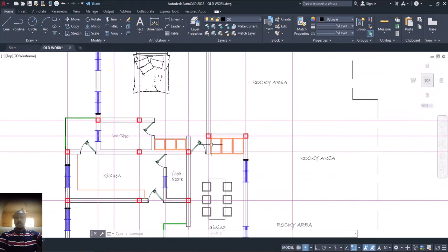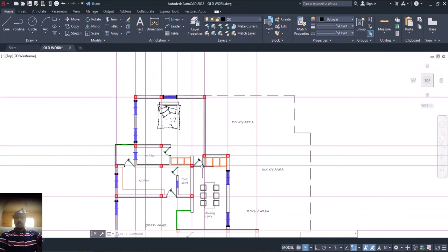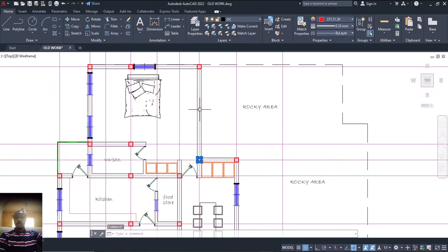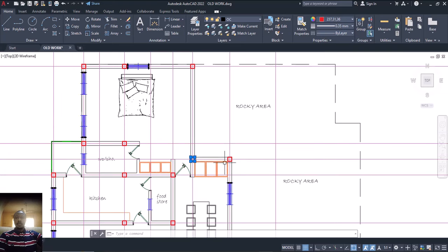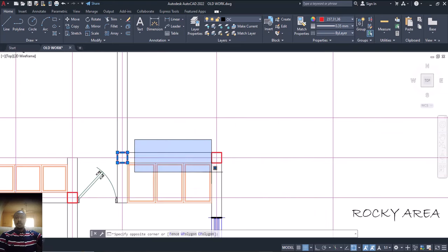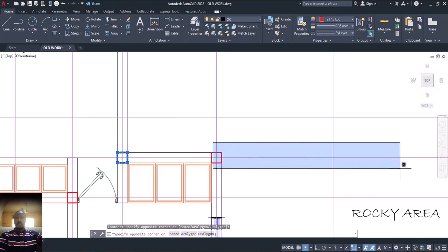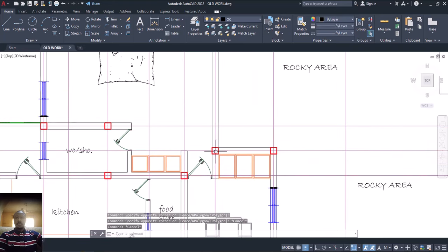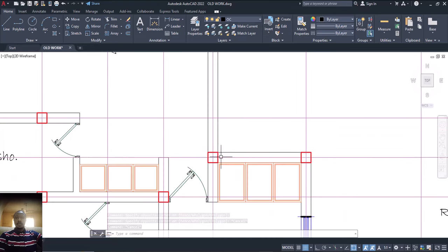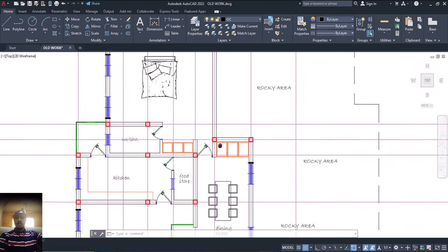Now looking at this place, they seem to be very close. But the way the architect does the drawing at times also matters a lot, because if I remove this particular column, where is this particular beam going to rest? And the beam coming from here is short, so it should be able to carry this one. But don't forget that this particular beam does not have any drop back at this stage, isn't it? So we need to support this place for safety. If care is not taken, it can fail. So it's better we just put it at this point. Is that okay? All right.